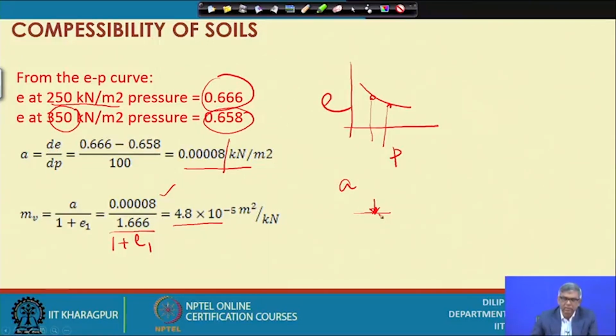Like that, for the second level of loading, the third level, for each level of loading you have to see till there is no change of thickness. From the end point, corresponding to each pressure, we get the thickness. If you know thickness versus pressure, then we can find void ratios, by a method we have mentioned already. In the previous lecture I prepared the table, and from the tabulated data of pressure versus e we plotted the e versus p curve.